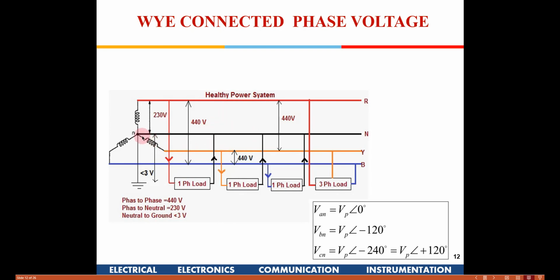Also, at the substation, or wherever the electricity is being generated, the neutral is grounded. For an ideal transmission line, there will not be any current flowing into this neutral wire if the loads connected are balanced. So there will be no IR drop in the neutral line. There will be no current flowing, but practically the loads don't get balanced exactly, so there will be some amount of current. But still it has to be within the permissible limit.